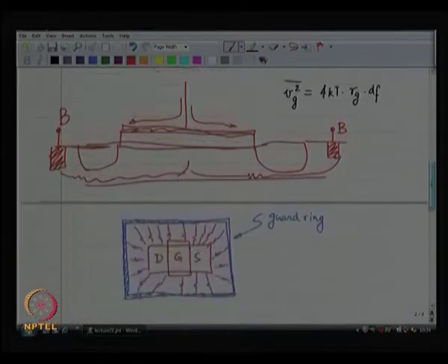Now, when we deal with noise, there are so many different noise sources, it is very hard to do the analysis in one shot. So, what we normally do is we use the principle of superposition and we analyze one noise source at a time and find the effect at the output, right. And then finally, once we are done, we sum up everything together and find out the total noise.